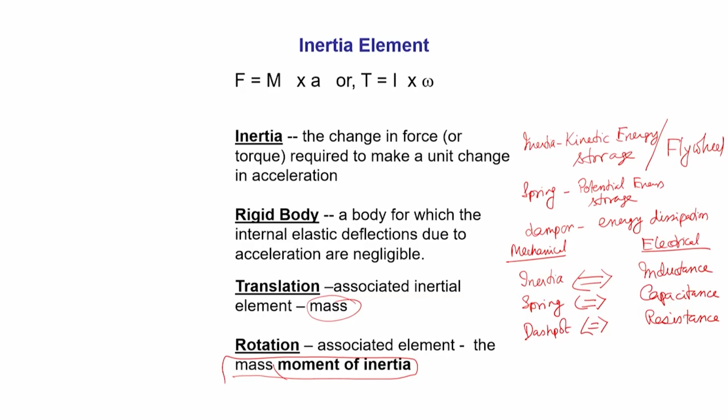Thus, we have broadly covered the different structural elements, and how they can be arranged in the form of a complete structure: tensile type, compression type, balance type, tensegrity type. I have also talked about the dynamic structure, how it can be designed in terms of three basic elements, the spring, the inertia system, and the dashpot, and how they can be arranged in series or in parallel.